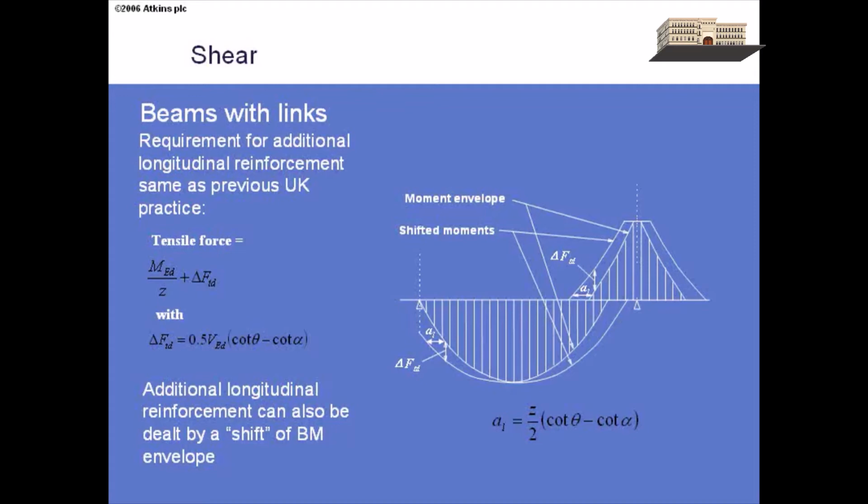if you think about it, the truss model is just that. It's a strut coming down, picking up a piece of reinforcement, and then a tie coming up and another strut coming down at an angle. If you make the truss angle flatter, you have to go further before it picks up the piece of reinforcement that you're considering. So it's all about extending the provision of reinforcement, not about adding at the points of maximum bending moment. So if you've got a short span and you don't curtail your reinforcement at all, say you've got T20s in the soffit and it's just 20s all the way through, this doesn't mean anything at all because you're not curtailing the reinforcement.